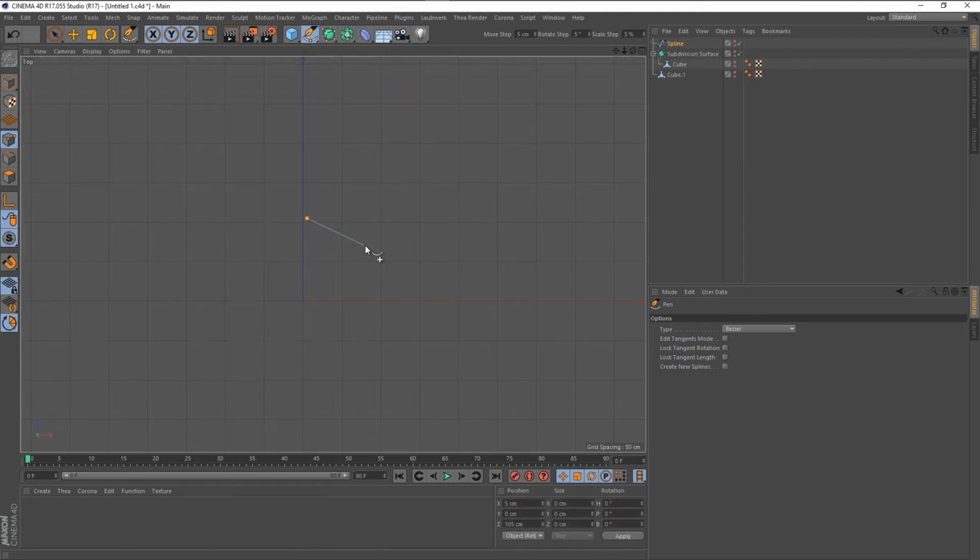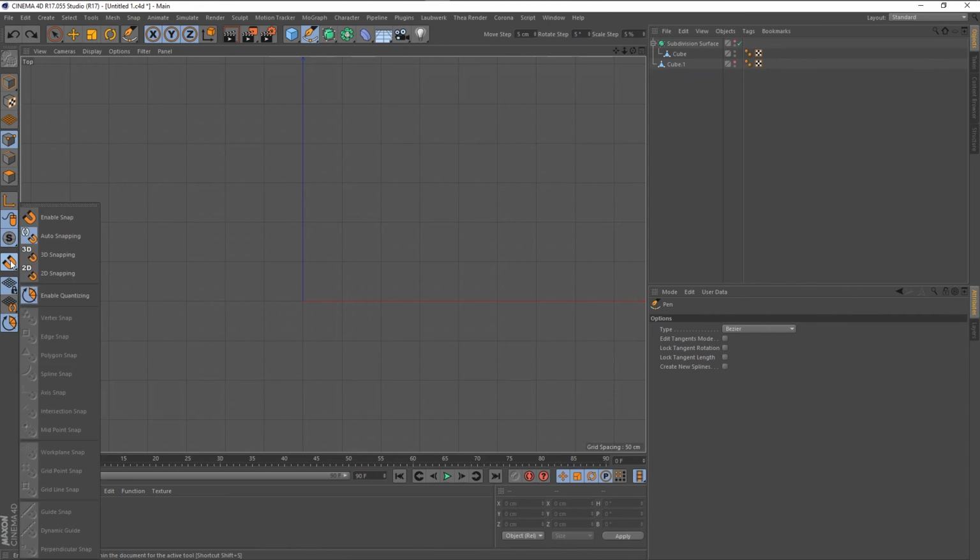Let's pretend I just wanted to get close and snap to, oops, there it is, there's the blue and the red axis, and I wanted to snap to that axis there. So I go into snap, and I just enable snap, okay, right there. You could enable it just by clicking on it. You can hit Shift S to enable it. And under that, now it looks like vertex snap is enabled, but none of these are enabled. So I'm going to turn off vertex snap, and it's so dumb that it disappears on you, but okay. And I want to turn on axis snap.